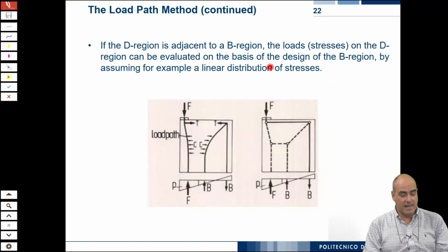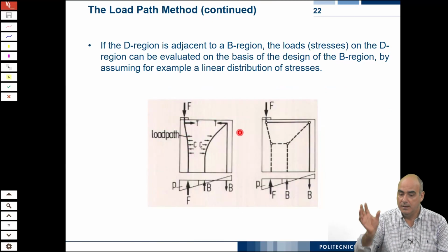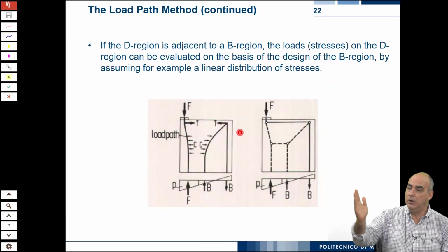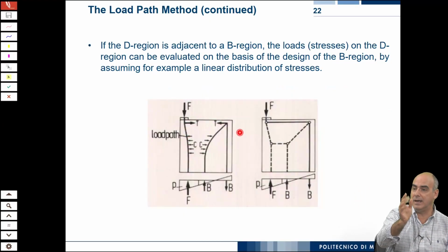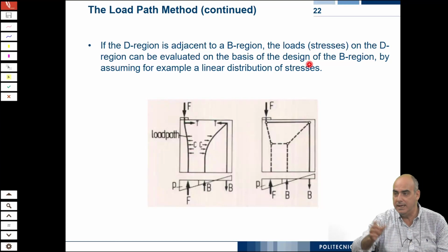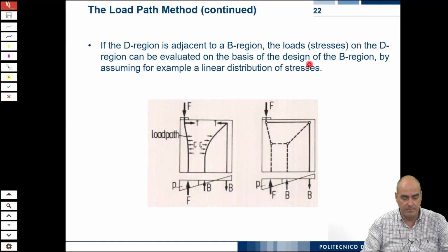This is another example. You can say that this can be the edge cross section of a column where you have the load applied with a very strong eccentricity. You see, the load is just at the edge of the cross section. It can happen in a building because you have different elements that have to converge on this element, and so they apply different loads.